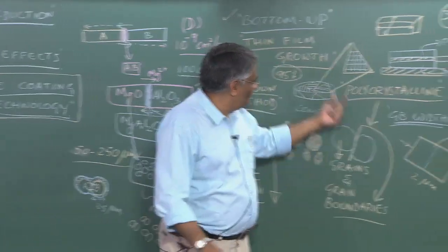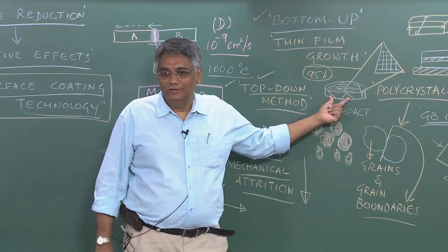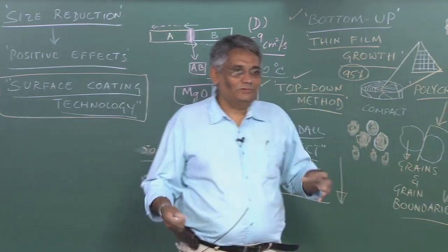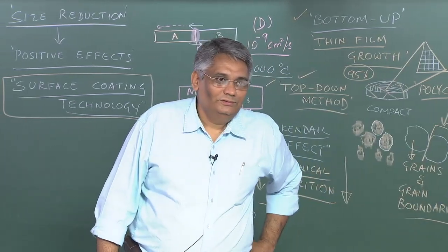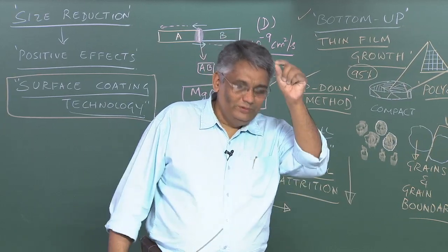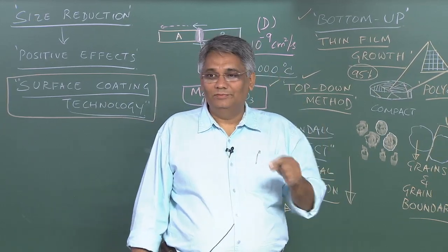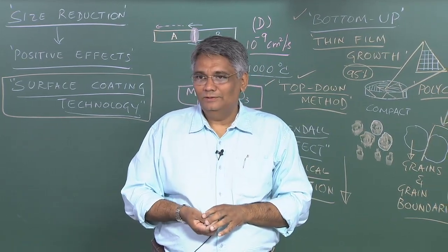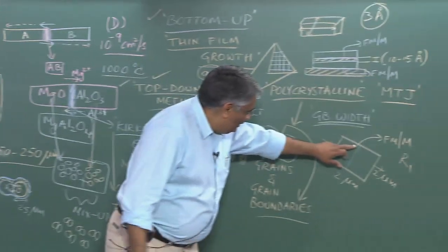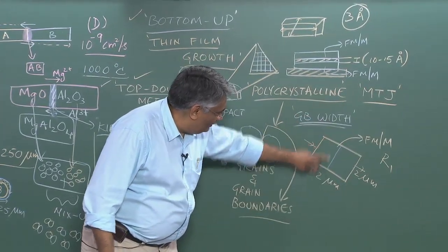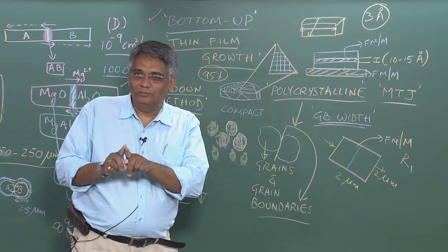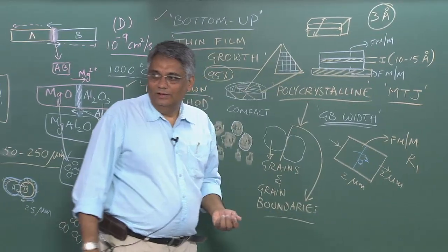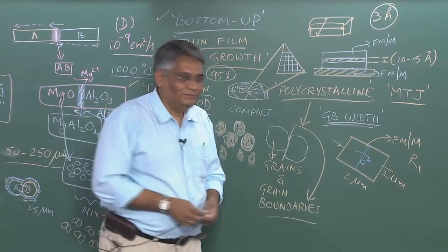If the grain boundary widths are like what you find in polycrystalline systems, the grain boundary width could be a few microns. Okay? So, if the grain boundary width is a few microns, or even if the width is in submicrons, still a current cannot tunnel through, is it not? So, ideally, if I create a very narrow grain boundary, I will then be able to make the electrons tunnel through, and I create what is called a tunnel resistance.